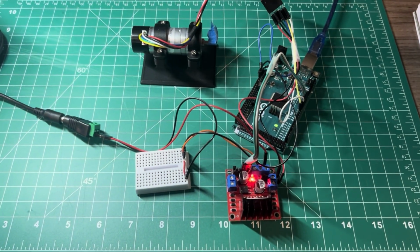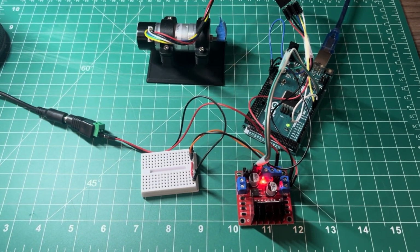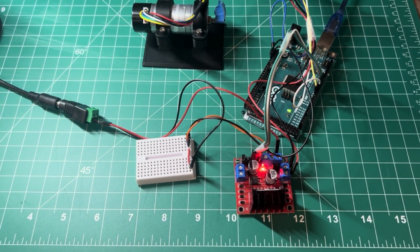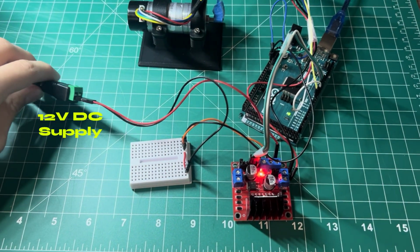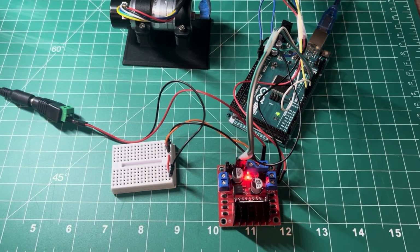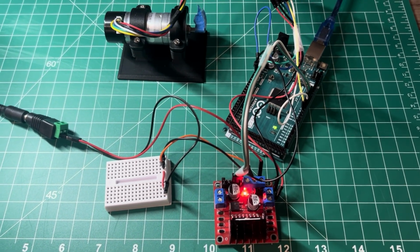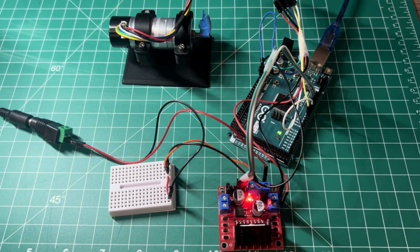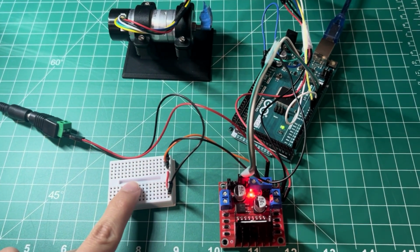To determine the transfer function of the system, experimental measurements were taken. Before we dive into the software, let's take a look at the hardware. At the heart of the setup is the Arduino Mega, which acts as the microcontroller that stores the control commands and sends power modulation signals to drive the motor. The entire system runs off a 12-volt DC power supply. To regulate that power and protect the components, particularly the Arduino, we use an L298N H bridge, which acts as a buffer, ensuring the motor receives sufficient current without overloading the microcontroller. Also, to prevent oscillating voltages and ensure stable operation, all components share a common ground.